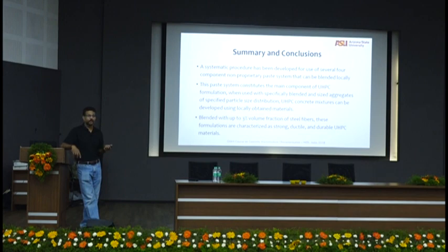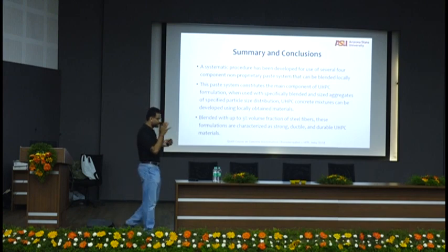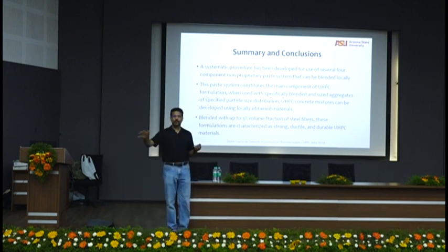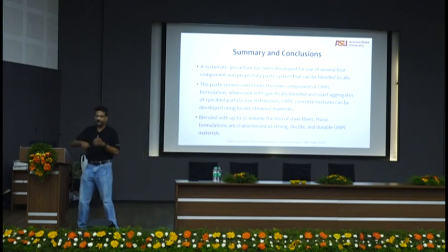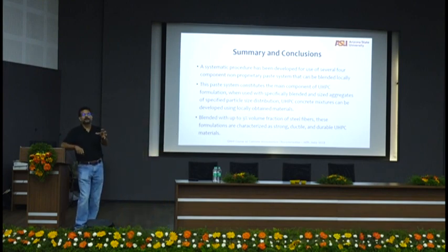The only thing is the mixing time is much longer. This concrete, right from the addition of aggregates all the way to final mix, is about 25 minutes of mixing. 25-30 minutes of mixing with very high admixture quantity. That's something that they had been trained on, and the addition of fiber. So we carefully organized what raw material will be added at what time, and we sequenced all of them, gave them a sequence chart, gave them a test procedure.